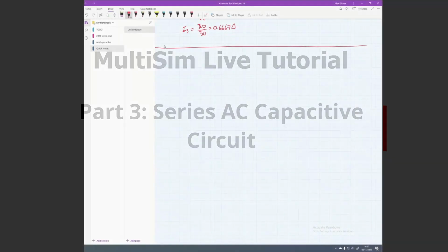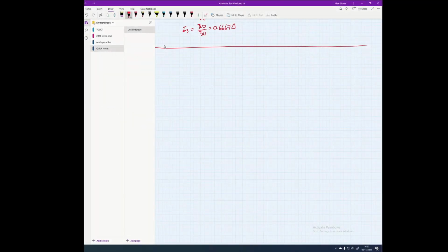So what we're going to calculate now is a reactive circuit. So we're going to look at reactive capacitance, and that's represented by the letters big X, small c. And XC is equal to 1 over 2 pi FC. Now the reason we call this reactive is because, unlike before where it was just DC, with these, the frequency,